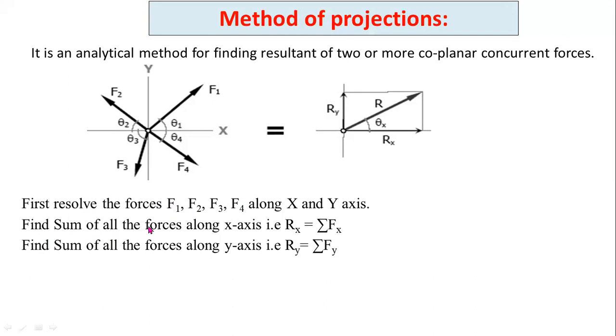And the second step is to find the sum of all the forces along the x-axis. That means the sum of all horizontal forces, summation Fx. Then you have to find the summation of all the vertical forces, that is summation Fy, the sum of all vertical forces along the y-axis.